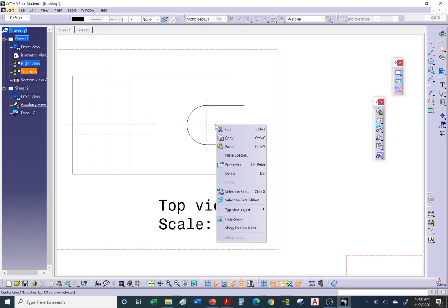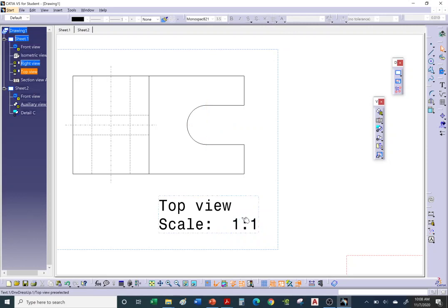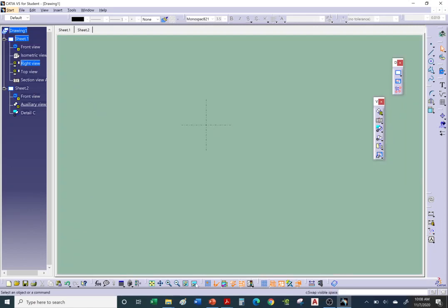Let's say instead of deleting this item, I wanted to just hide it. Let's say I wasn't sure if I wanted the center mark. Instead of deleting, you can hide it. You can go to hide. There it is. I hid that center mark. You can always click on the no show. So here we can swap to no show. You can always call it back. There it is, the center mark. It's in the hidden layer.